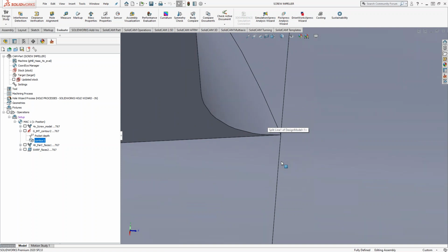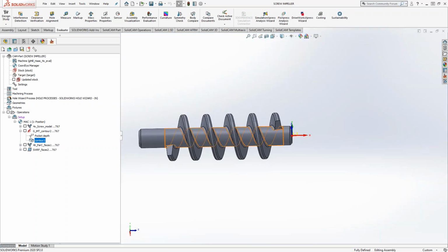The way to think about how you do wrap geometry is, and it's a weird example, but in these times everybody's going to have one, an empty toilet paper roll. If you were to cut that and unravel it, you would get this nice looking strip of paper. But when you roll it up, you get this conical shape. That's exactly how you should think about it. If you look at how it's highlighted in orange right there, that's essentially just a continuous pocket wrapped around the rotary. So when you do wrap geometry, think of it like that. By doing that, I program it the exact same way I do with 2D iMachining.